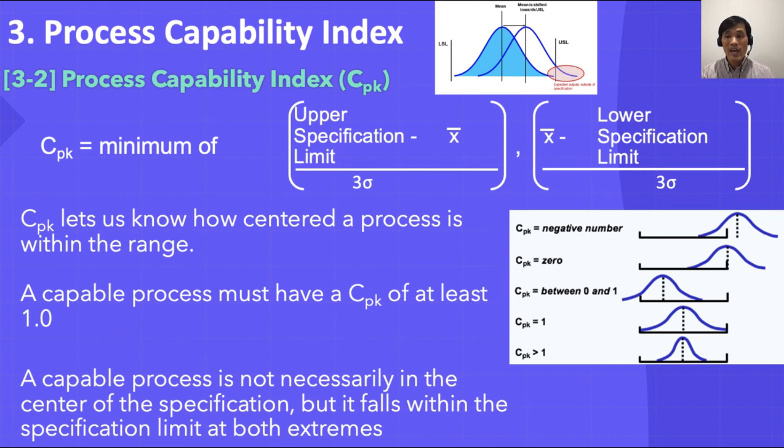Cpk is used to estimate how close you are to a given target and how consistent you are around your average performance. Cpk gives you the best case scenario for the existing process. It can also estimate future process performance, assuming performance is consistent over time.